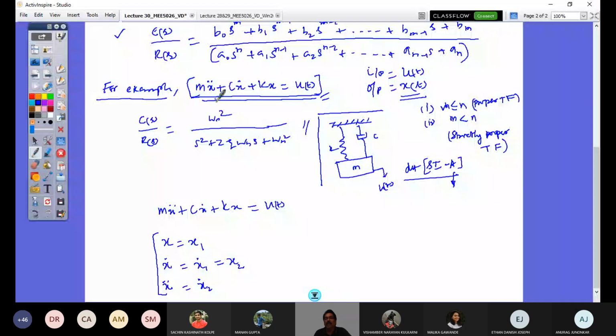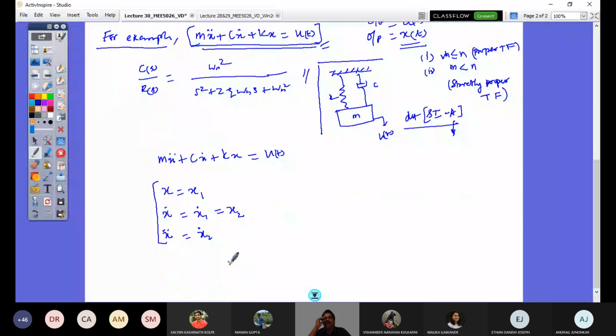That is what we straight away deduced in our bicycle model. In the bicycle model, we had v dot and r dot, the two equations: Fy is equal to m(v dot plus r u), and then the second equation, Mz is equal to Izz r dot.